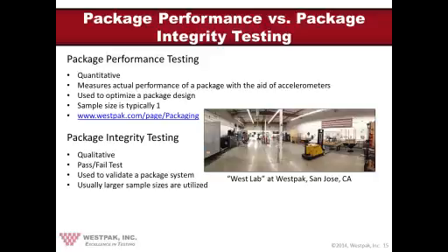It can also be done to determine the resonant frequency of the package system and compare it with the natural frequency of the bare product. Package performance testing is often used to optimize a package design and takes an in-depth look at the actual numbers. Package integrity tests, on the other hand, which is the focus of discussion here, is strictly a qualitative test to see if the product will get to its destination in one piece. It is usually a pass-fail test in association with the test standard it's tested against.